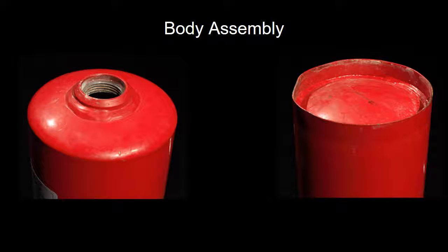The body assembly is comprised of the body, base, and valve bung. After the 3 parts are made, they are welded together. Based on the appearance of the weld and simple part geometry, it was determined that gas metal arc welding was used in combination with an automation process. These methods would provide a lower cost for a high production rate.